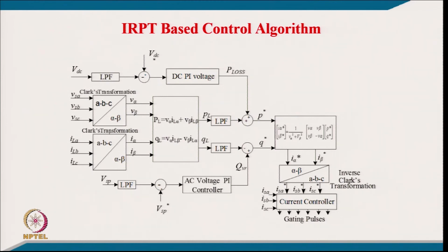So, again we add this active power of the load along with the loss of the D STATCOM; this active power has to be drawn from the supply. So, this is the active power drawn from the supply, and similarly we have the voltage regulation here. We have a reference amplitude of the voltage to be maintained at the point of common coupling across the load, and we have the estimated peak, and we use a low pass filter because there may be ripple. Then we use the PI controller, the voltage controller, which gives the reactive power to be generated by the D STATCOM.